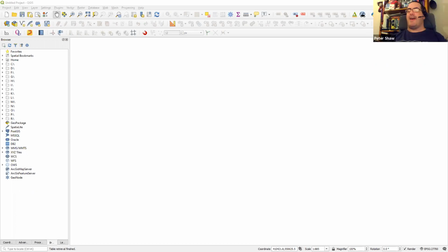Yeah. So what you've done there is you've pretty much clicked on it and added it as a layer to your document, but you've added it as a full-size countrywide layer. So what your copy of QGIS is currently doing is trying to download every single raster tile for every area of the UK that map covers. No, we don't really want to do that, do we? And each of those tiles are only 256 pixels by 256 pixels with about an inch to a mile. So right now it's probably sitting trying to download in excess of about 4 million graphics tiles. So we don't want it to do that, really, do we?